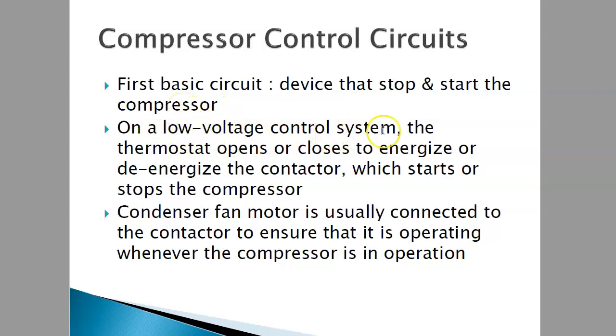On a low voltage control system, the thermostat opens and closes to energize and de-energize the compressor contactor, which starts and stops the compressor.